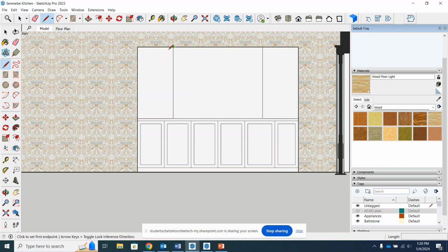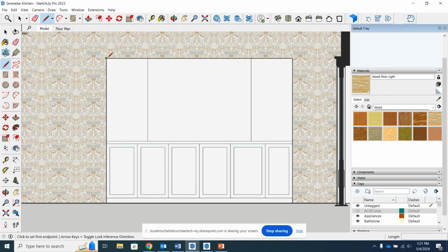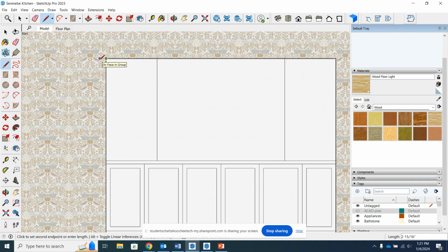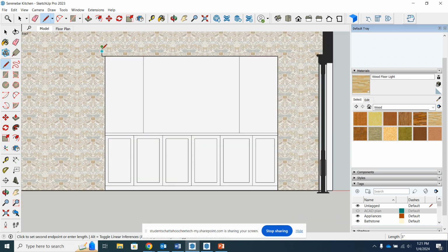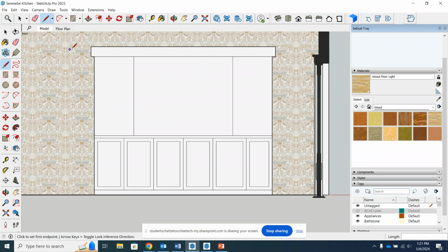Then at this top, I'm going to come over 2 inches and then go up 6 inches. I'm basically creating what's going to become my header trim. Do some math, 9 foot 4 inches should put me where I want it. Come over, and that's added that.